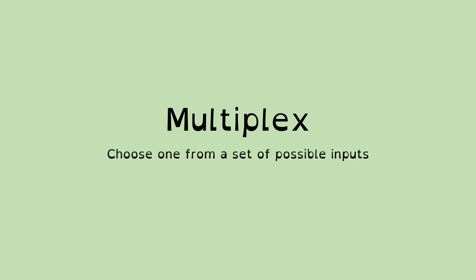So as I was saying, this short series of videos within that context are about multiplexers. So far, we've developed various configurations of multiplexers. But I want to talk about where to go as we go further down this issue of interconnecting signals and interconnecting components, which is something that we're going to need to do if we're creating a CPU. A multiplexer, as I said, is a way of choosing which input you're going to use. Thinking theoretically about a fairly simple 4-bit CPU, you might have a number of different inputs for each component, and so you want to choose from a set of components.